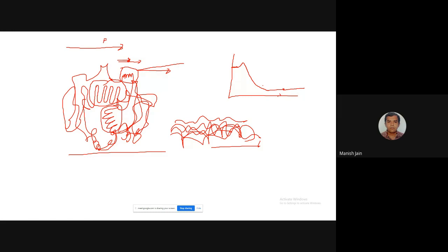Okay, so this is the example of polymeric melts. Similarly, if you see colloidal solutions, suppose you have a very dense colloidal solution like jam. In that solution you have very big particles of solid material, and in between you have liquid. Okay, so what will happen? At very low shear rate, the material will again behave as a bulk. It will flow as a Newtonian fluid.